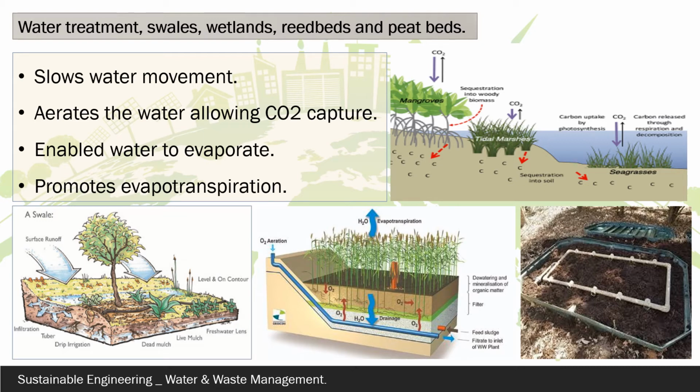If you have units like septic tanks, where you are treating the first line and second line waste, which is settling within the tanks, the water that comes out of them can then be treated in a peat bed to reduce its impact on the local ground. The peat will treat it, reducing the phosphorus levels within the water to a level that can be pushed out into local streams and rivers without it polluting the local environment.